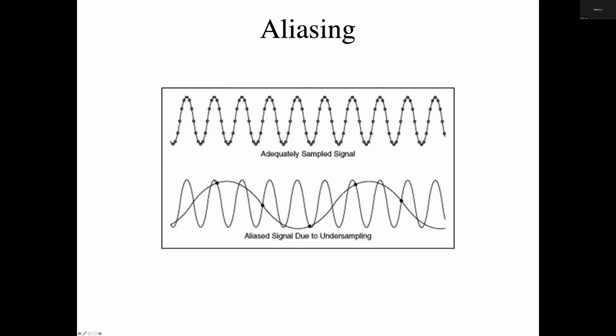And so I'm not sampling with high enough frequency to measure those higher frequency oscillations. But when I ask what sinusoid I've sampled, it comes out as a lower frequency. It looks like I've sampled power in the signal at a lower frequency. And this is the concept of aliasing. Okay, so that's misrepresentation of high frequency power in your signal, and it looks like it's a lower frequency.